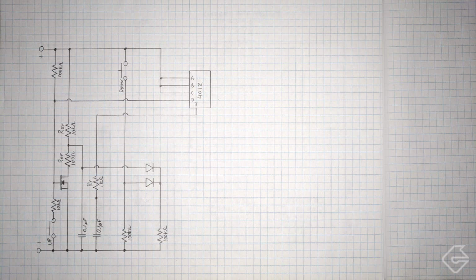So to put the LEDs in, it wasn't all that complicated. The down was actually quite easy. All I did is I added in our light up LED right over here with basically a resistor of any size I could choose in order to get us the nice good brightness over here. The up was a little bit more complicated because remember, our up is inverted, so I needed to use another MOSFET to make sure that the light turns on when you push the button.